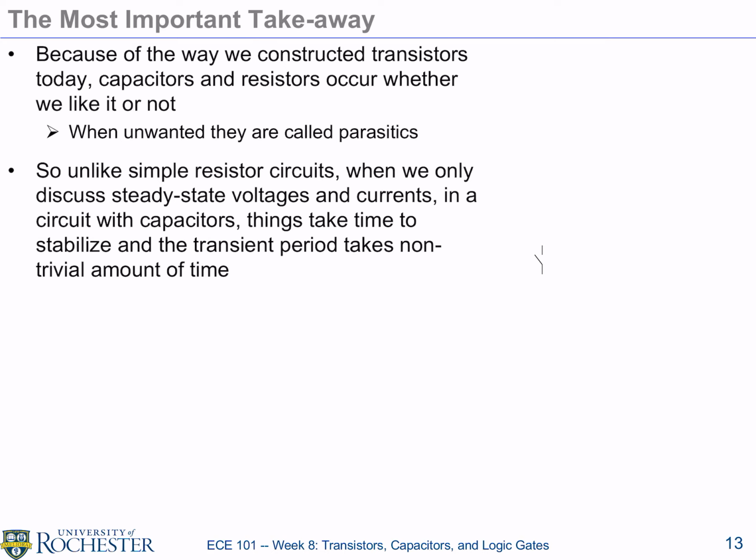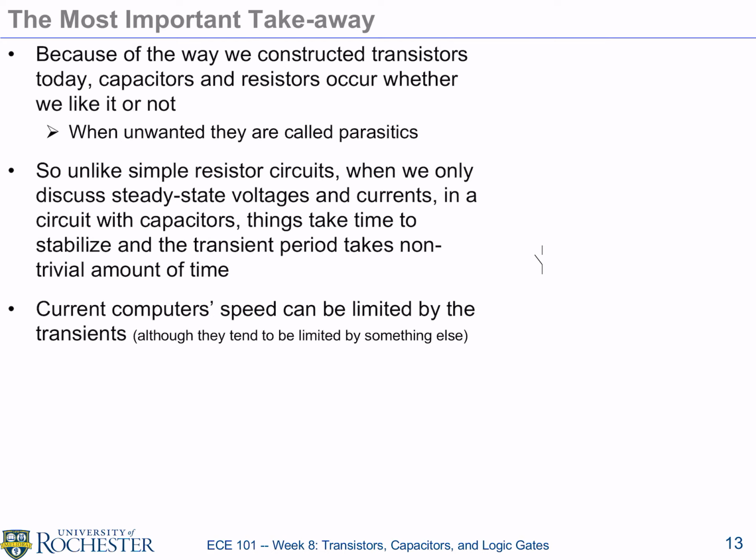So even with this simple circuit, the steady state solution, the reality is there is this charging path that is an RC circuit, and it takes time, even when, let's say, one node has a very sharp voltage transition. As time goes by, it goes from 1, boom, to 0.